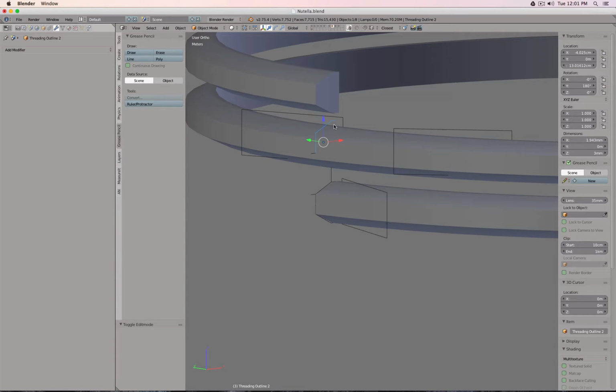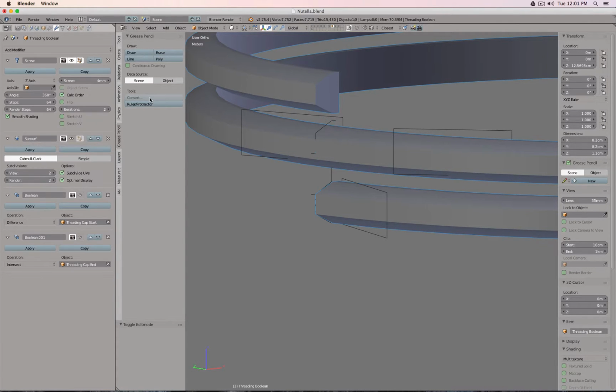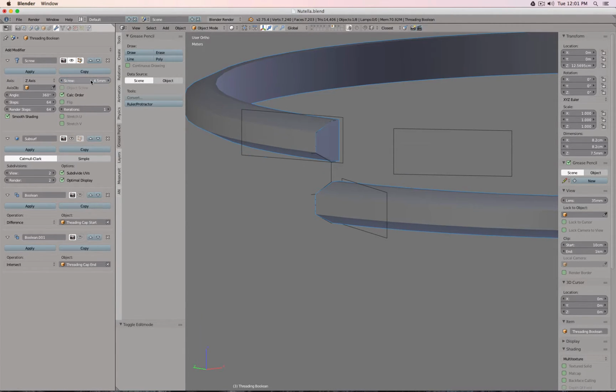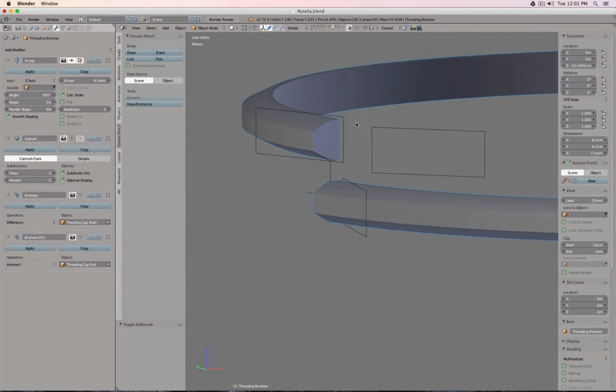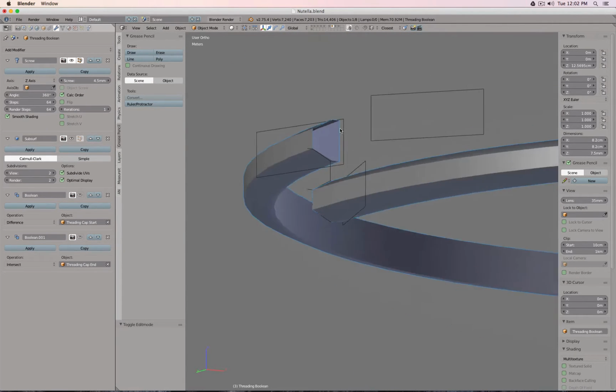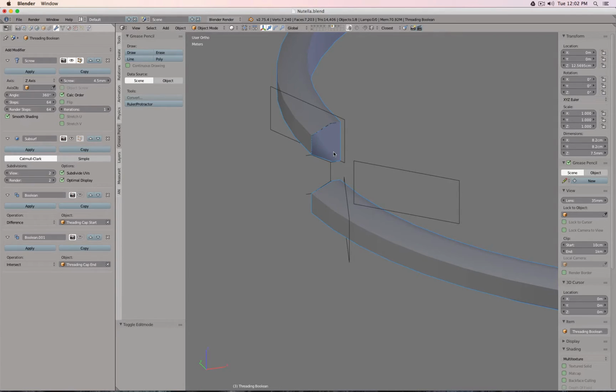You see here's the start, there's kind of like the end or the midpoint. So if I do just one, you can see that better. So 4.5 millimeters there. So now I know that the distance of my threading probably will be good, and there will be a nice and tight, maybe too tight, catch between the bottle and the cap threading.